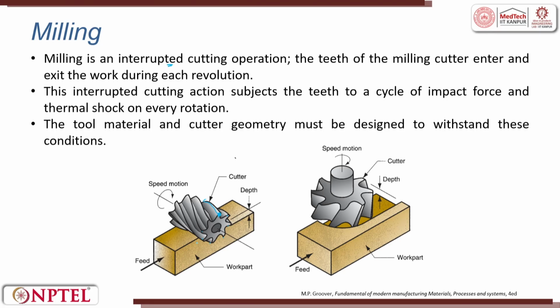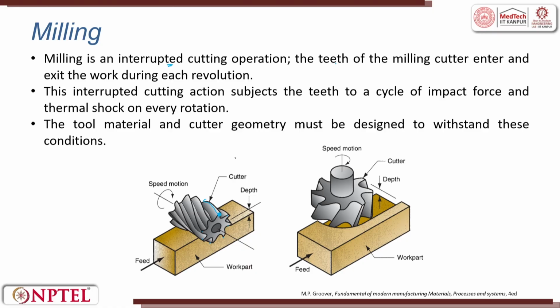So, interrupted cutting means that every time it cuts, then the next cut, and the next cut. So, there is always a phenomenon of vibration, as compared to that of a lathe machine. The teeth of a milling cutter enter and exit the workpiece during each revolution.